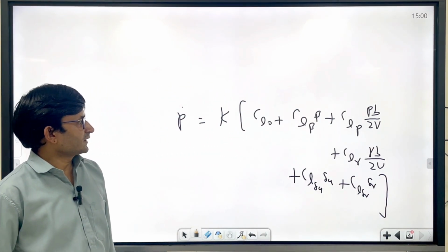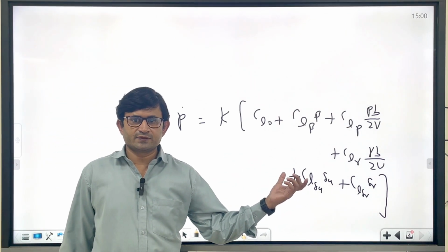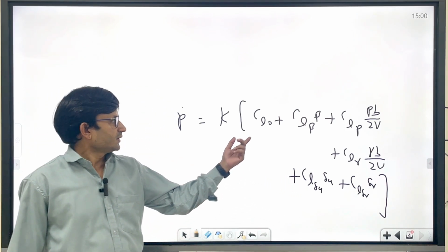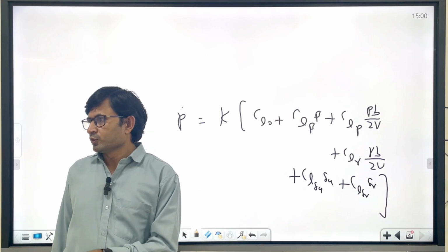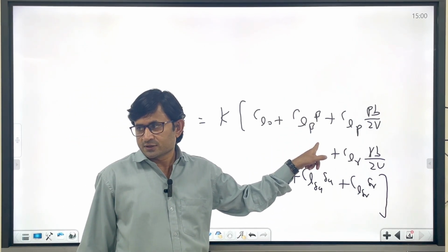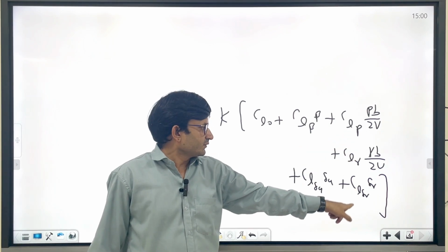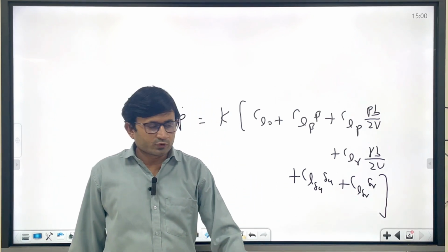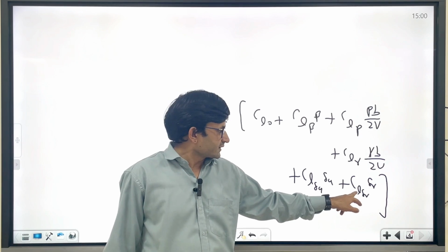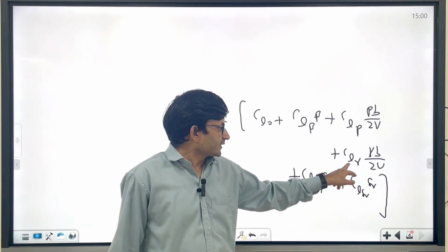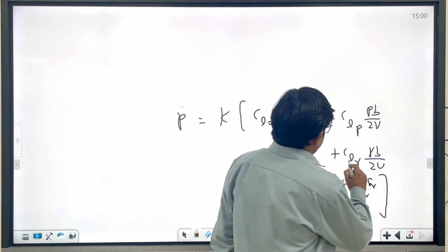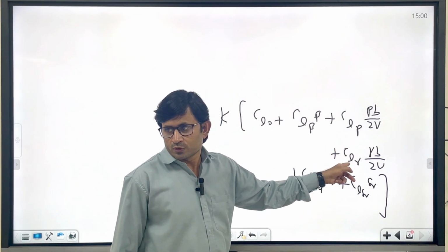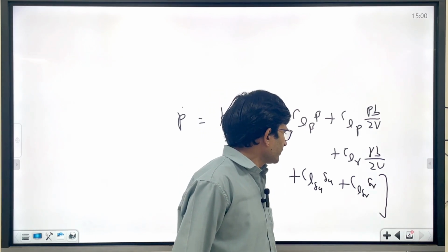In the aircraft design course I have talked about this. This is nothing but the aerodynamic model representation in the roll case, where CL represents the rolling moment coefficient. CL beta is the stability derivative, CL p is the damping derivative, and CL delta A is the aileron control power. When there is coupling involved, when you deflect, there will be roll, which is why CL delta is written. And CL r similarly gives roll. So this is the complete aerodynamic model.